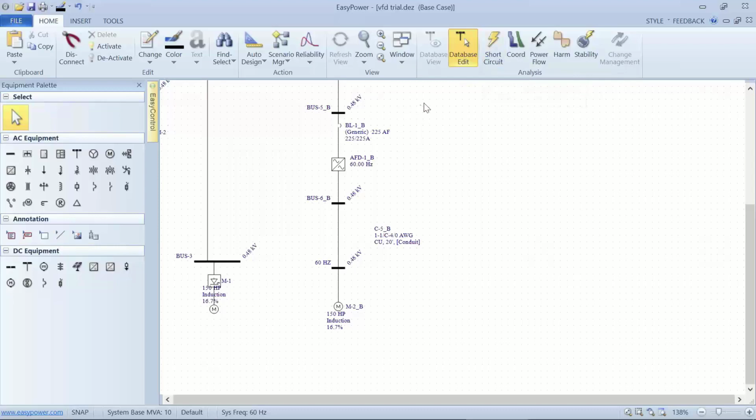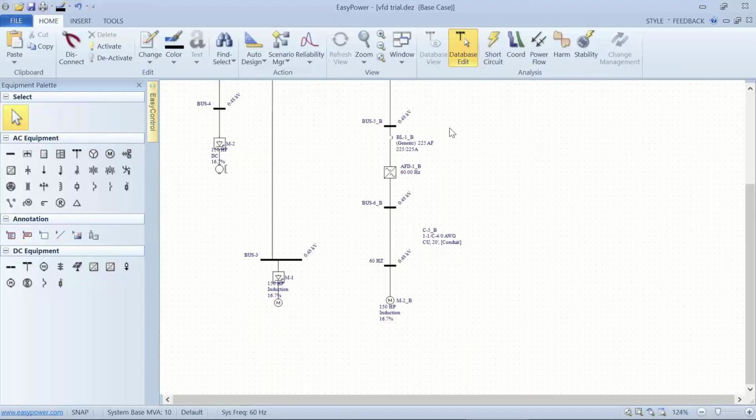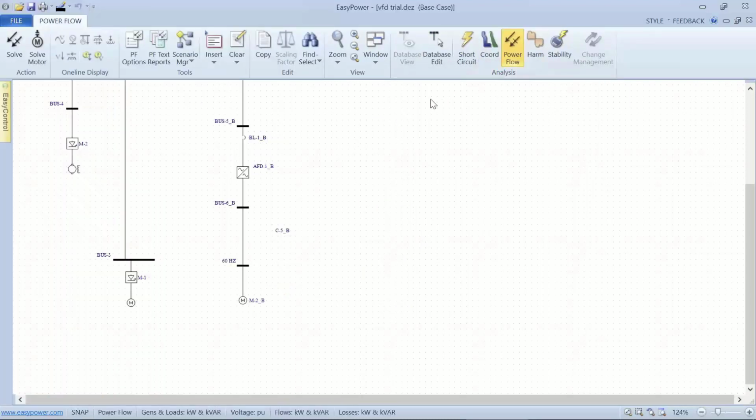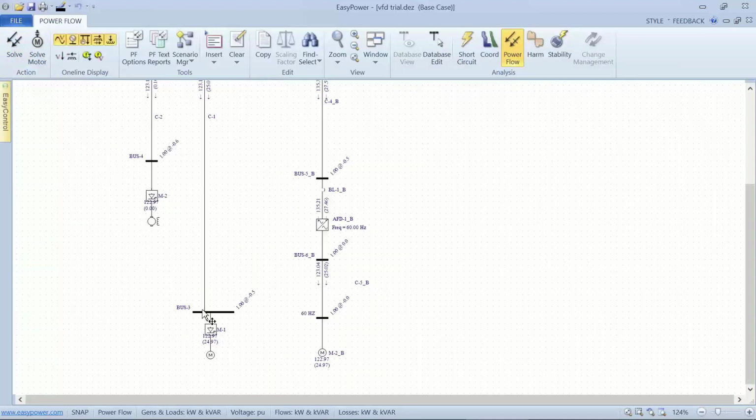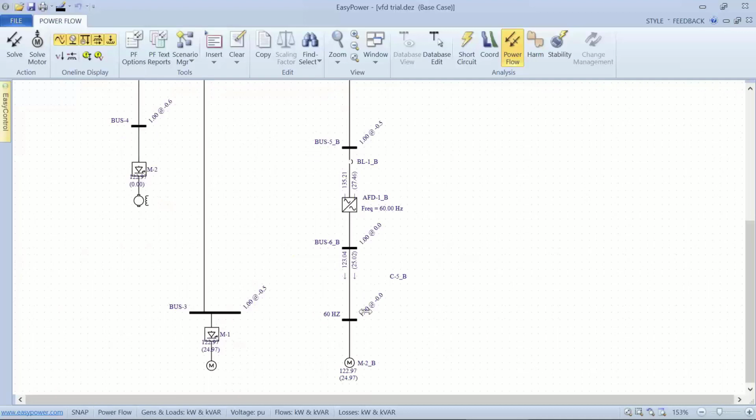So that gives us the benefit of doing a 60 hertz power factor solution, and it shows the power flow around the individual motors. We can show here we have a 1 per unit voltage in both cases and a slightly different power angle upstream of the controller, but it matches what we have set up on our two systems.